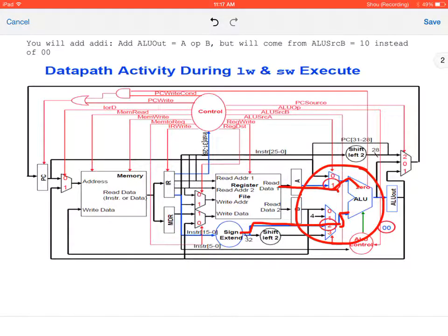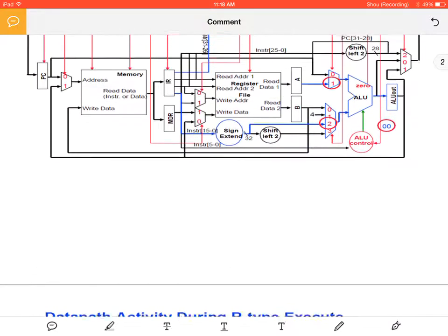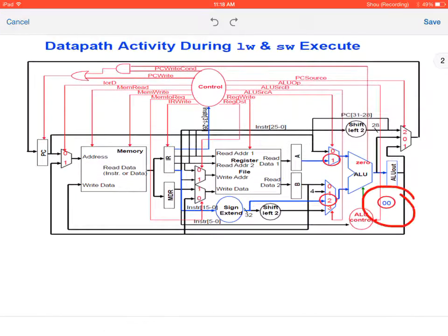So think about it in C or C++, right? You have a base pointer of the array, and the offset, if it's A of like 3, is calculated using this value. So 3 would be here, and 1 would be the base pointer of the array. So that's calculated in this third stage in a load or store instruction. And again, it's circled, so I should indicate it. We're also sending it 0, 0 if it's load or store word because we want to add in the ALU.